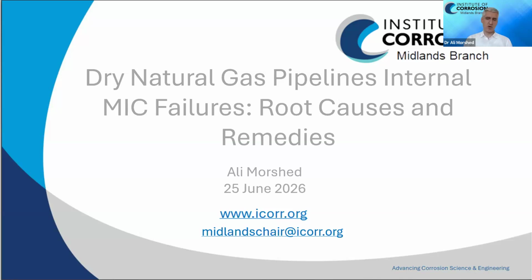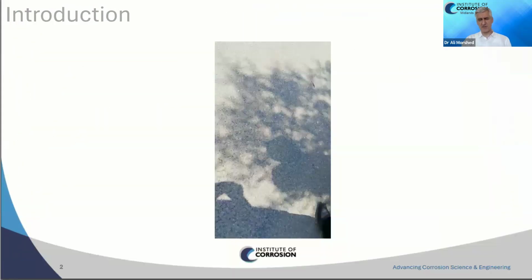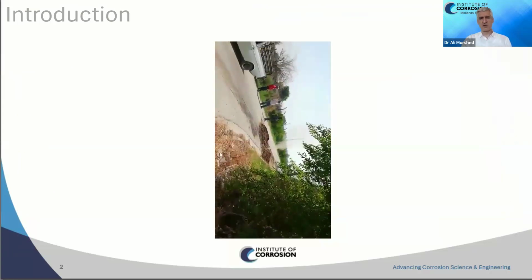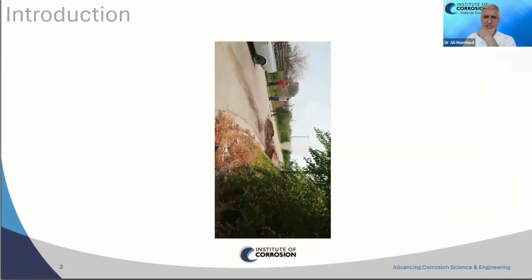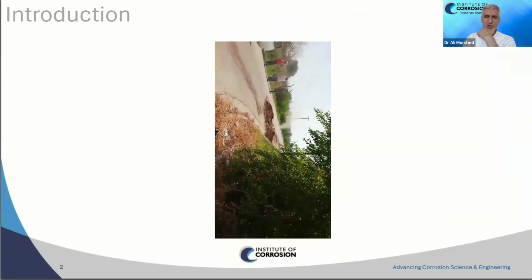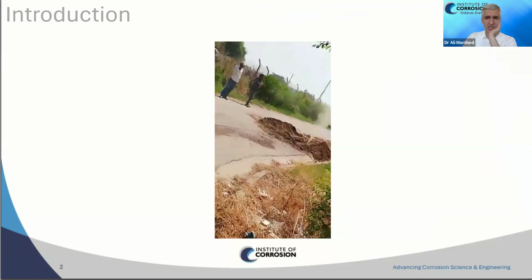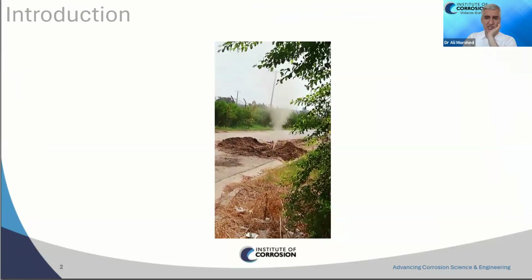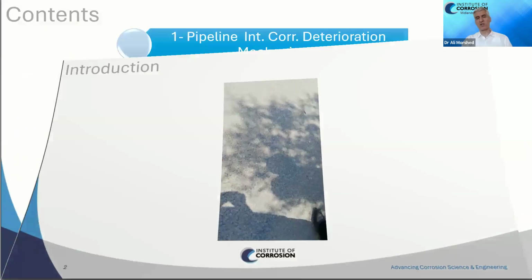So what I'm going to do is briefly discuss MIC. And here we have footage of a gas leak we had on a rural road. As you can see, the gas is gushing out. Unfortunately, we had quite a number of failures because of MIC. And it became a challenge for us to find out where the water was getting into the system and where the bacteria were going into the system.